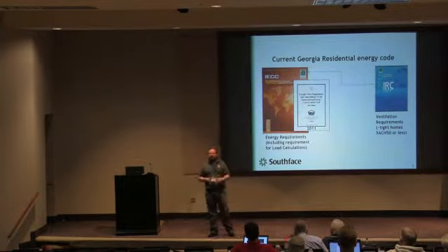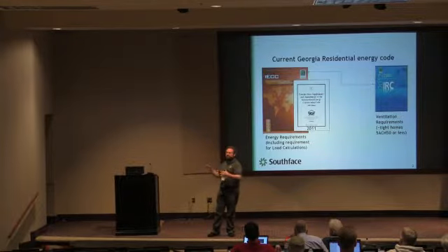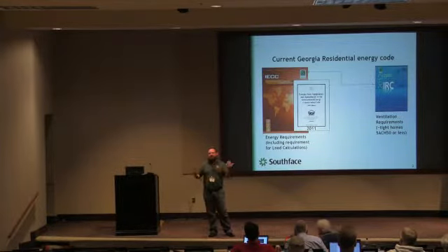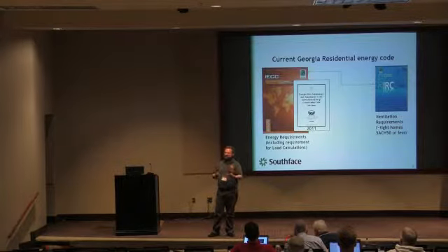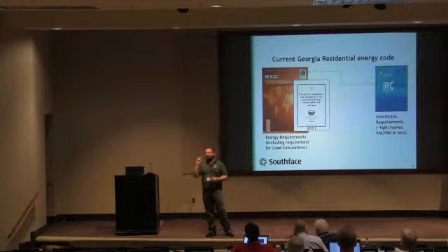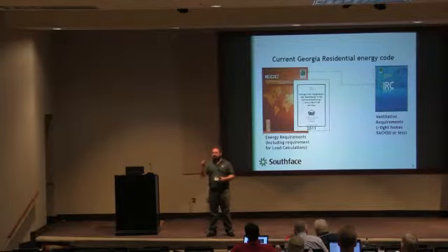But the load calculation is a function of a whole lot of other things going on in that house, as we'll talk about. And really, if they're going to replace equipment, they ought to assess the existing home and determine the tonnage that it needs and not just do a one-for-one swap. That's particularly true when they've done a spray foam roof line renovation.